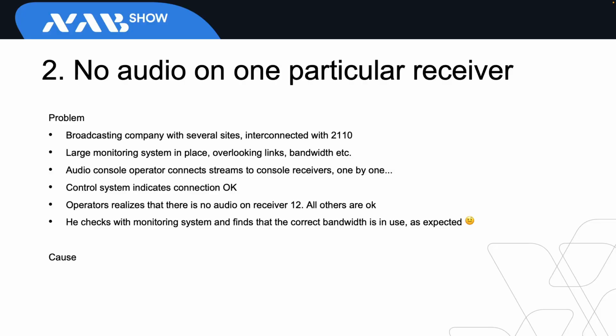Now, in this particular case, this is the explanation, basically just the summary. It turned out that receiver 2 was never intended to receive; it's set up for a low latency connection. It was never intended to be connecting to a sender which is on the other side, at another site. And the latency doesn't allow the packets to arrive on time. So basically all packets arrive, but too late. And in this case, that's probably a translator booth or something.